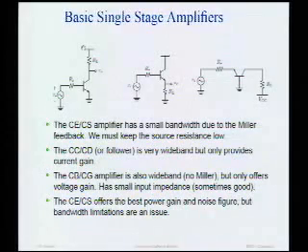There is feed-through from the input to the output, which does produce a zero in the transfer function. But it's actually not temperature stable, right? And it varies a lot with process, right? So if I have this, the gain of this device is GM times R. GM varies over temperature, it varies over process. R varies over temperature, varies over process. It's not a very robust amplifier, right? If someone says, give me an amplifier that has a power gain of 10, and you give them this, it's going to vary all over the map. So how do we fix that? Feedback, right? That's right. Okay, good.